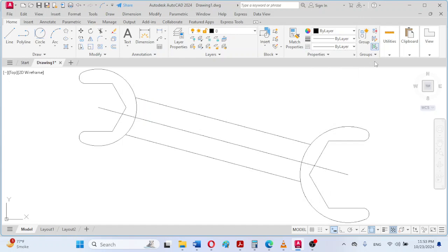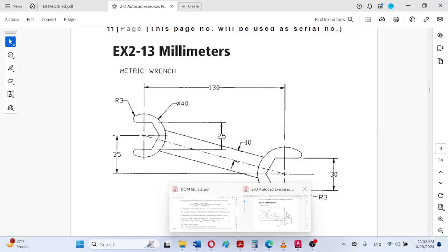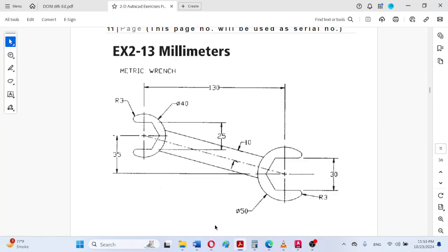Now, how to apply it: we first select this line, and then from this pull down list we click on center, and in this way the line will be changed into center. Our next task is that the scale is much larger. We want to reduce the scale so that the center line looks somewhat similar to this.